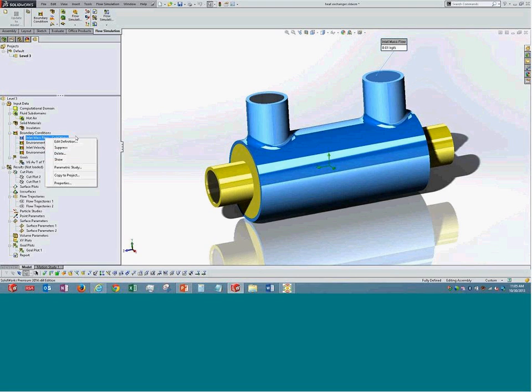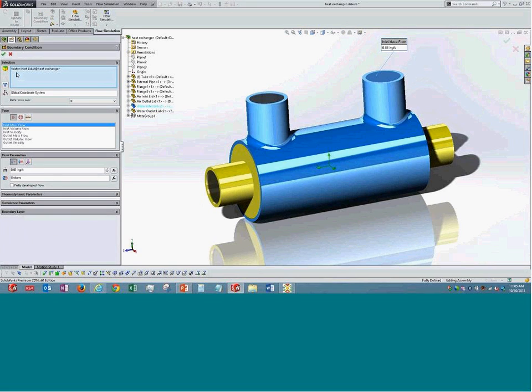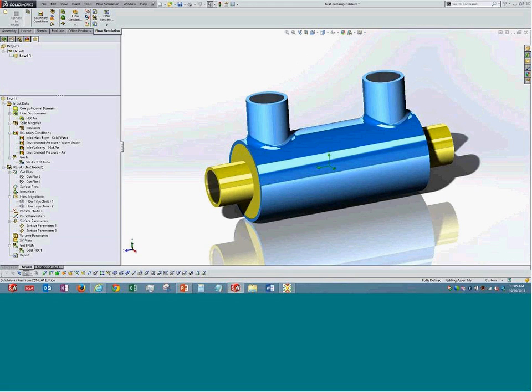The second is the hot air, which is entering over here. This air is going to dissipate certain heat to the liquid, that is water, and when it goes out, it will go out at a certain temperature. Apart from the flow rate, we are specifying the initial temperature of the cold water and the initial temperature of the hot air. So the outlet temperature we calculate after the analysis is done. And over here, we are just specifying the average temperature of the central tube, which could help guide the entire analysis. So we create the setup, and if I go into the results, it is something like that.